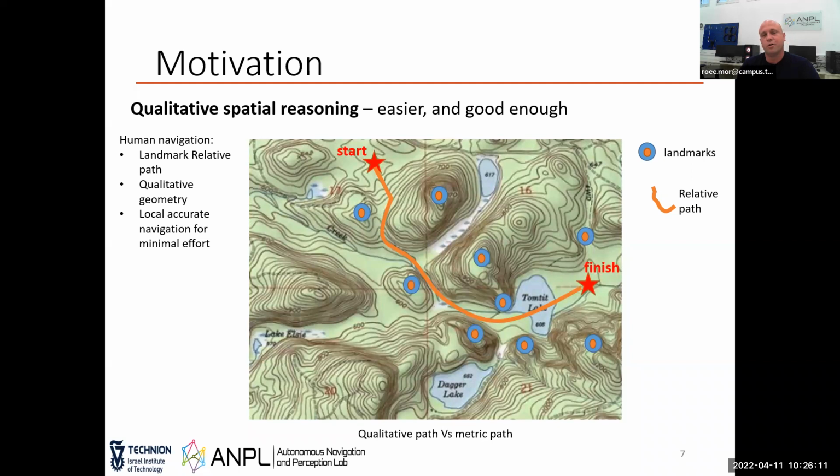I'm just going to use landmarks I can track, for example, the hilltops or other salient landmarks. And then while I'm navigating, I'm just going to reference myself to these landmarks I can see at each time. So it's relative navigation. It's not going to be a global navigation to know exactly where I am on the map in each second.